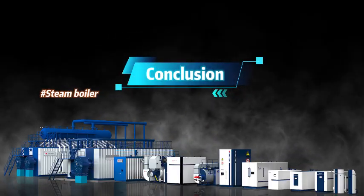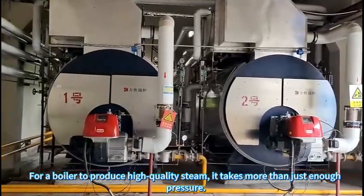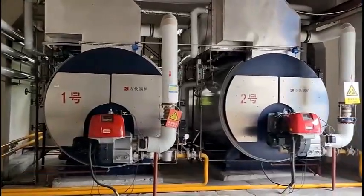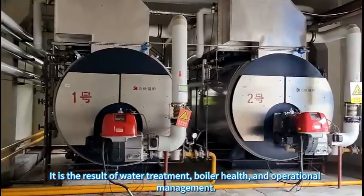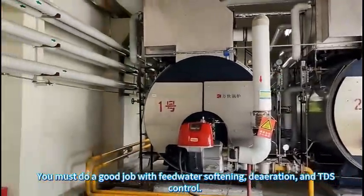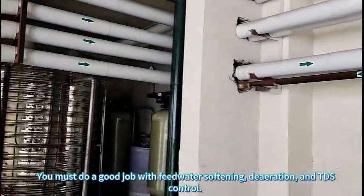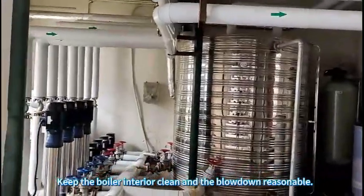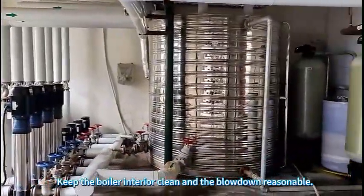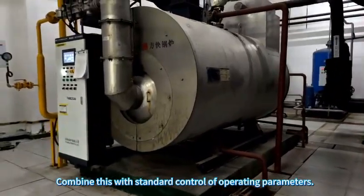Steam boiler conclusion. For a boiler to produce high-quality steam, it takes more than just enough pressure. It is the result of water treatment, boiler health, and operational management. You must do a good job with feedwater softening, deaeration, and TDS control. Keep the boiler interior clean and the blowdown reasonable. Combine this with standard control of operating parameters.